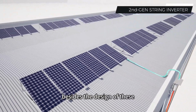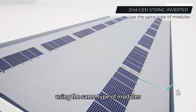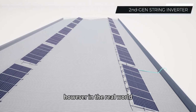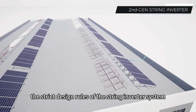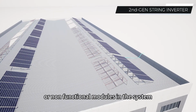Besides, the design of these systems requires that all strings with the same length, using the same type of modules, be positioned at the same angle towards the sun. However, in the real world, the roof condition would not be perfect. The strict design rules of the string inverter system will lead to a waste of roof space or non-functional modules in the system.